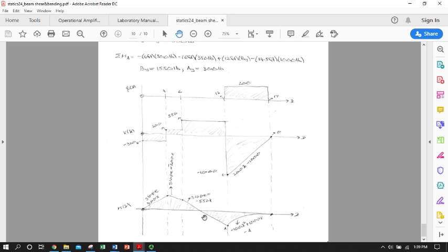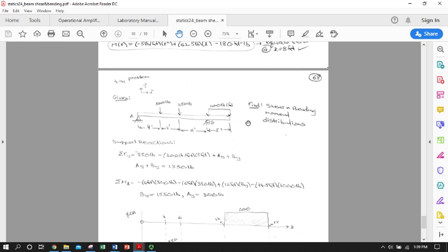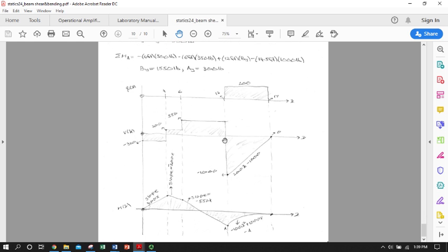Kind of interesting. So it's going to continue on a line until we get to that support B, and now we've got a huge step function in shear, but no step function in moment. We didn't apply a point moment. We didn't apply a point twist. But due to the distributed load going forward, we're going to have a parabola with coefficients and signs that are basically the opposite of these, with this being the first derivative of that.